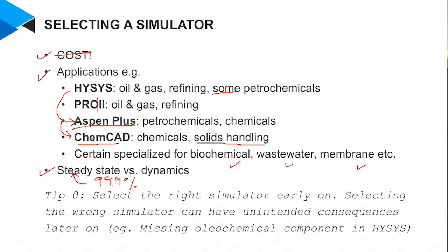All right. So tip 0. I call it tip 0 because this is the tip before you start. Select the right simulator early on. Selecting the wrong simulator can have unintended consequences later on. For example, you don't have this component in HYSYS.